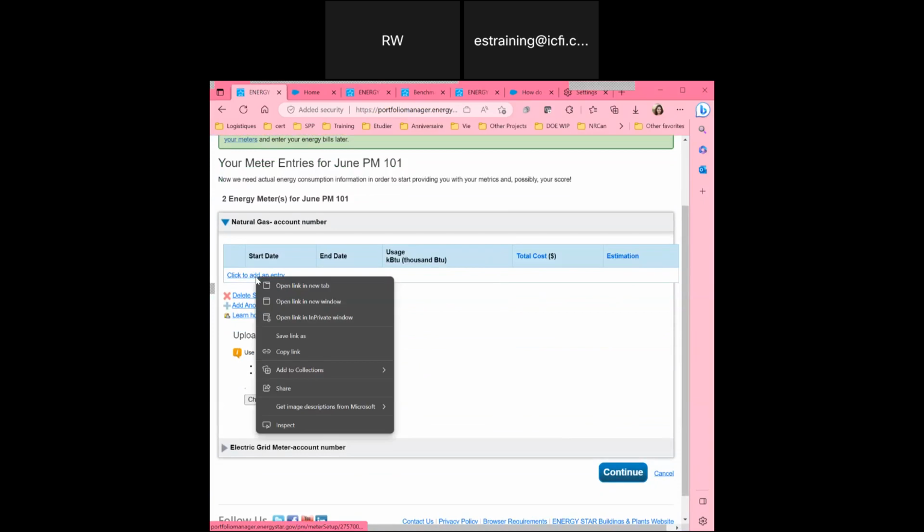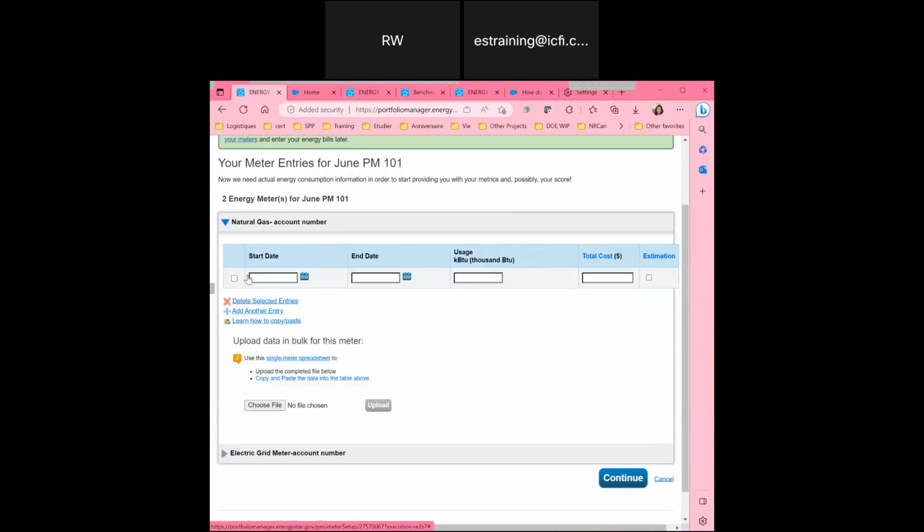All right, so for this one, we are going to enter the start date for natural gas. So that was going to be 2022. All right, so then that means Portfolio Manager is going to auto fill this. So if, for example, this is wrong and it's through maybe the 14th of February instead of the 1st, you can always edit that. I'm just going to keep it because it's fine. And then you are going to enter your usage, and you can also enter the total cost if you want to. And if this is an estimate, then you can also check that box.